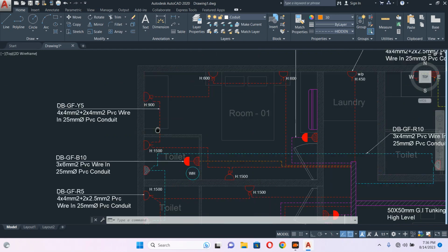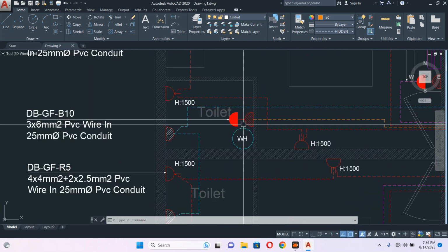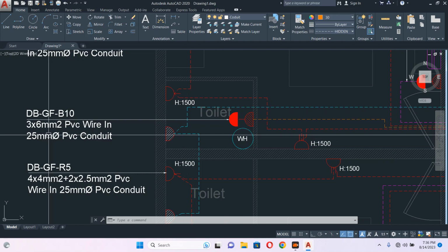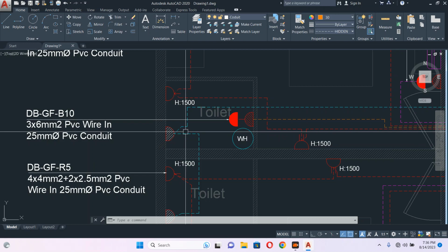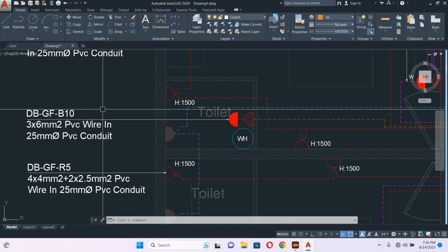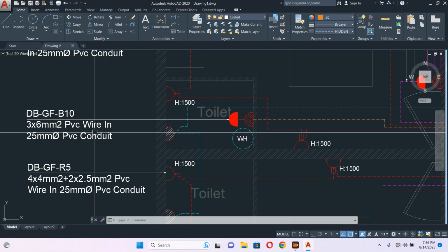Let's say this example. I told it's almost 12 ampere. So for this 12 ampere, maybe a 2.5 wire can handle it. But if you see in Qatar, they use bigger wire, maybe 3 by 4, also big. If 2.5 can handle, they will still put the bigger one.